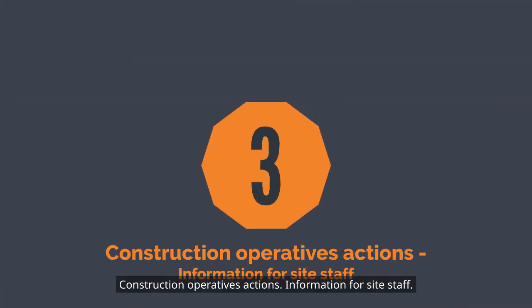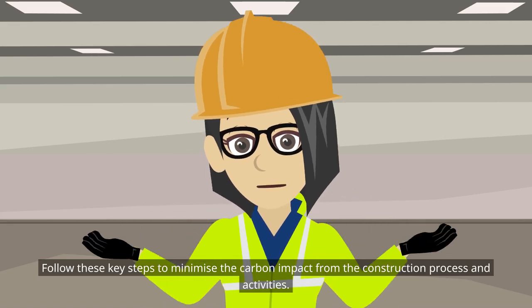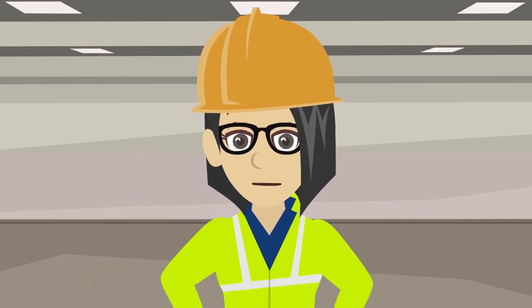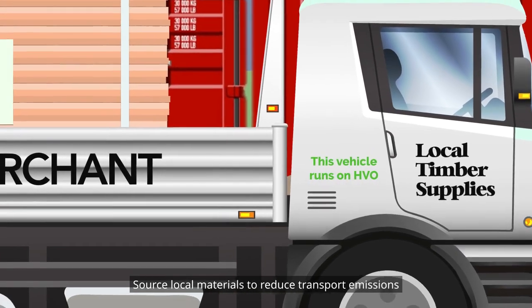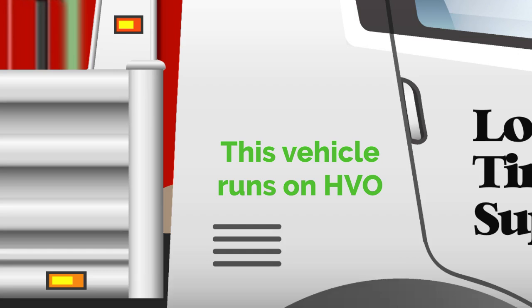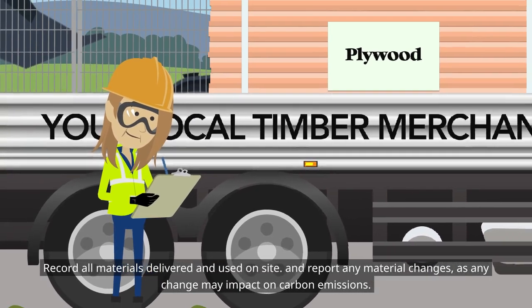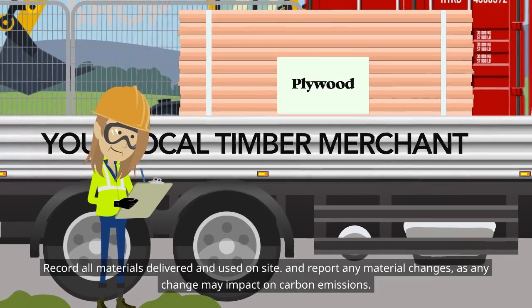Construction operatives actions. Information for site staff. Follow these key steps to minimize the carbon impact from the construction process and activities. Source local materials to reduce transport emissions. Request low-carbon transport to deliver materials. Record all materials delivered and used on site, and report any material changes, as any change may impact on carbon emissions.